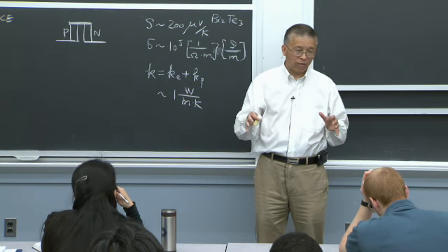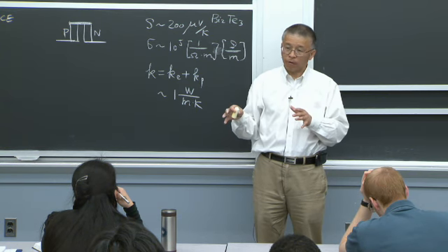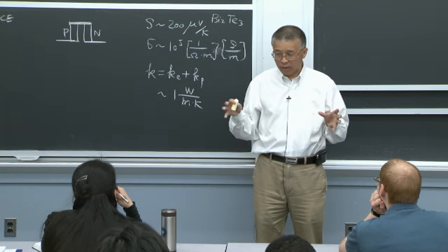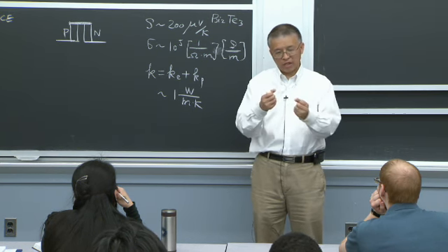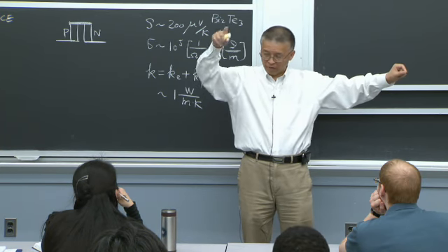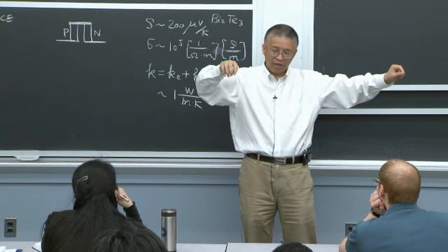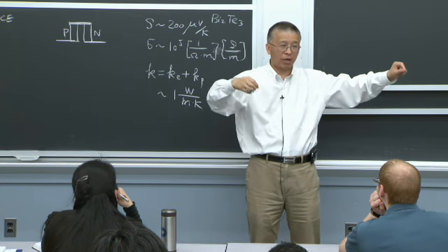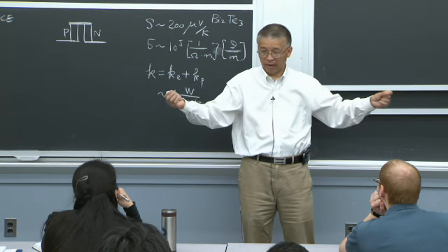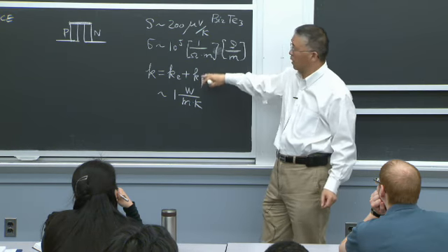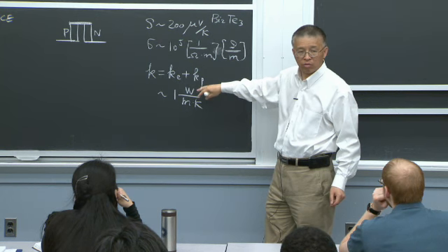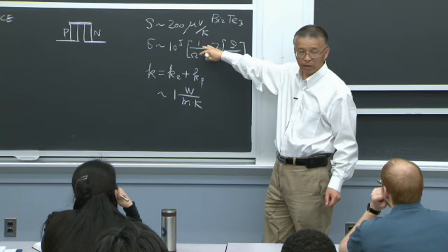The mass scattering. For example, silicon's thermal conductivity is 150, germanium's is about 90, and then when you mix the atoms together, the mass difference matters. If you think about an atomic chain, if each atom is the same, you get a very harmonic vibration. But if at each mass point you put a different mass, that string is not going to vibrate very well. That's the mass difference scattering, alloy scattering, and that's the typical way to reduce the thermal conductivity. And of course, you want to do it without reducing the electric conductivity.